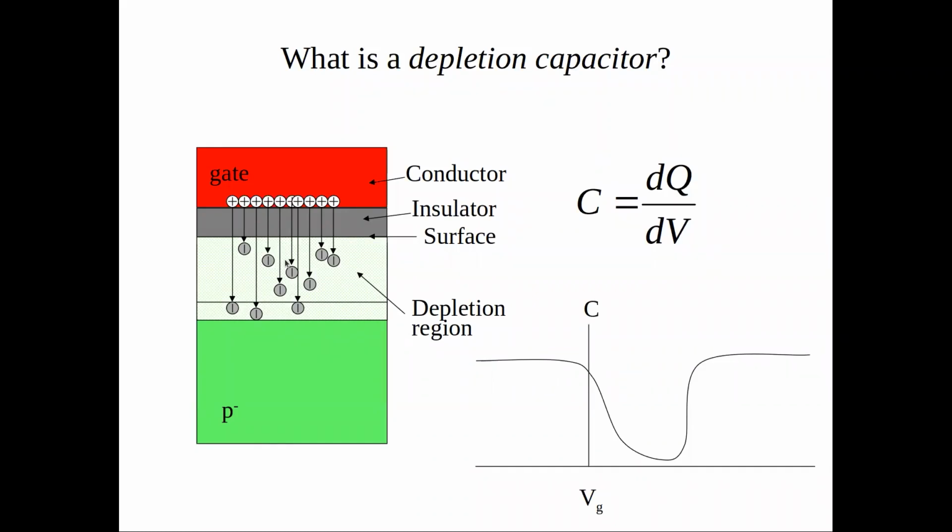Well, let's say I fix VG to 0, and I have some depletion region. Then I fix VG to 0.5, and that gets wider. So you have three new fixed ions, yes, but it's like taking snapshots at steady state. I'm not moving VG back and forth. I fix it, and then I have a snapshot with another VG, and then another fixed VG.